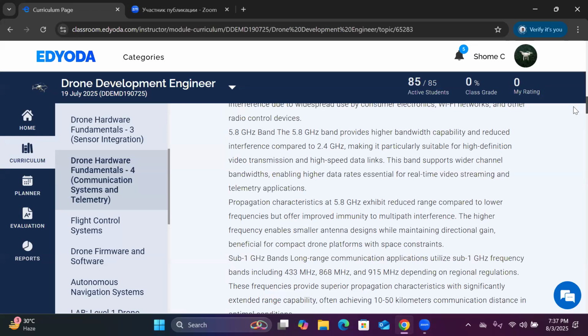Does it mean that higher frequency, smaller antenna should have the omnidirectional? No, it does not mean always the same. You can use omnidirectional antenna, but for higher bandwidth or for precise data streaming, you need to use the directional antenna. In directional antenna, you can get more gain.